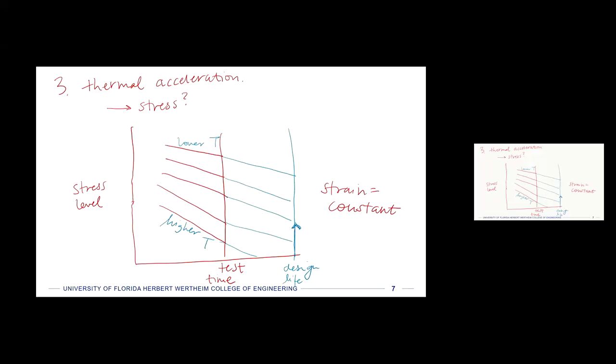So we do a whole suite of temperatures, and then we say, oh, I think my situation is going to operate at kind of this temperature, and then I can take that over and get the allowable stress. So this is a way of doing experiments on particular materials that might be used for design, right? This is not, we don't have equations coming out. This is not predictive. This is just how the measurements were taken and then how they're plotted and what can be done to sort of use plots directly. Okay.